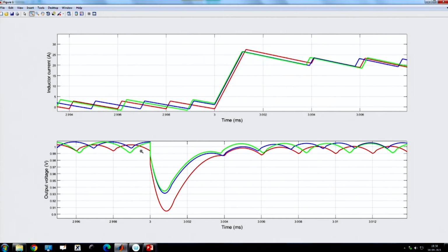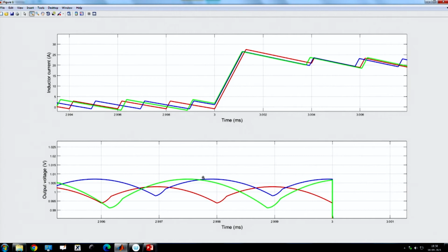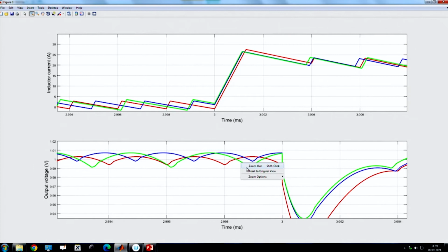That means the large signal tuning, and particularly the current based sliding mode control we have designed using all large signal tuning. That is why they are giving almost optimal recovery time, but only due to the shift of this average voltage. So, that is why there is a shift in the output.